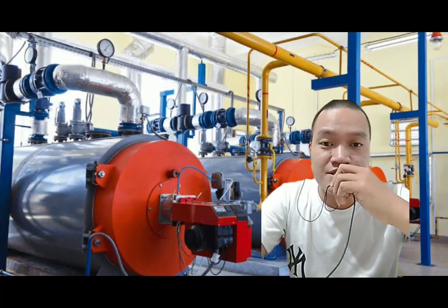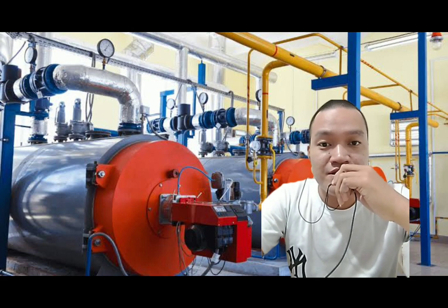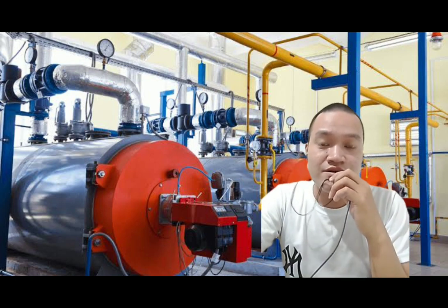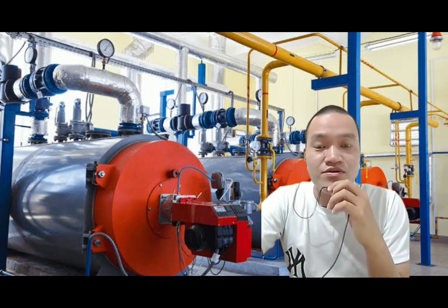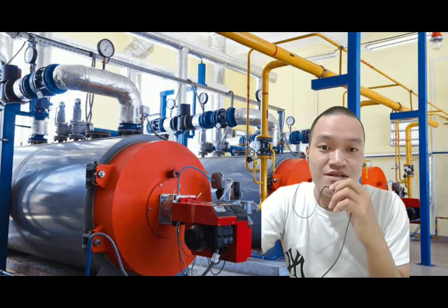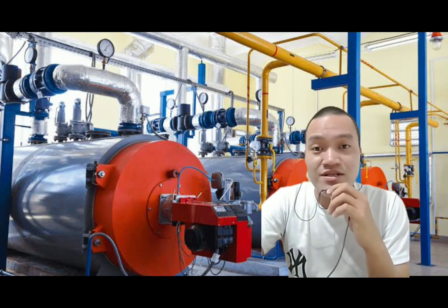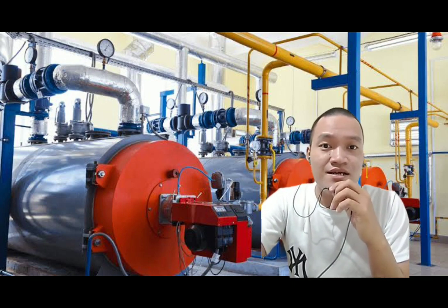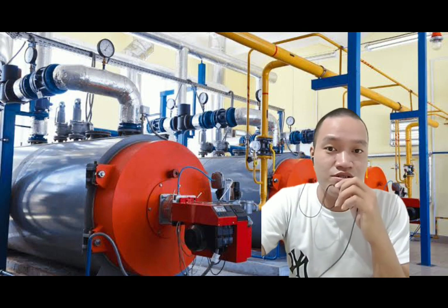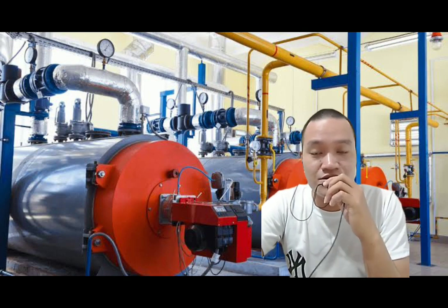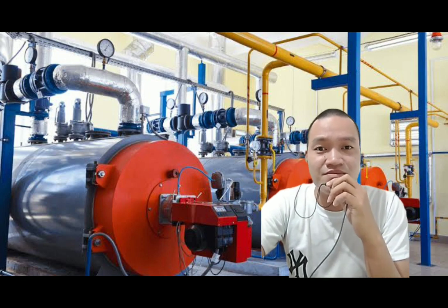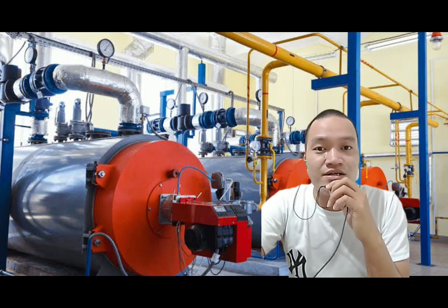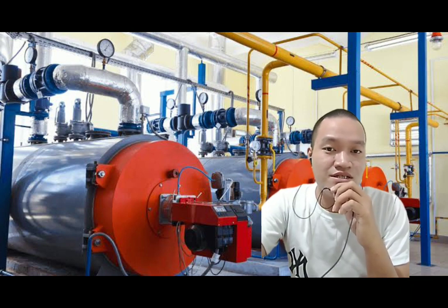The next topic to discuss is the operating principle on how to fire a boiler. First, you must check all the parameters in the boiler before operating it, like the water level in the water level gauge, fuel level in the fuel day tank, switches in the control panel, and the voltage in the main boiler board. You can also conduct a lamp control test to know if the lamps are lighting or in good condition. So after that, we are now going to supply feed water to the boiler.